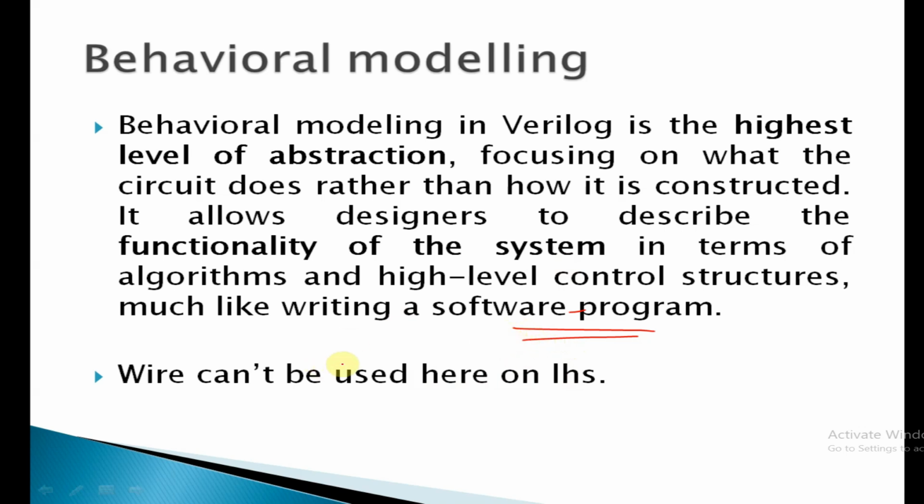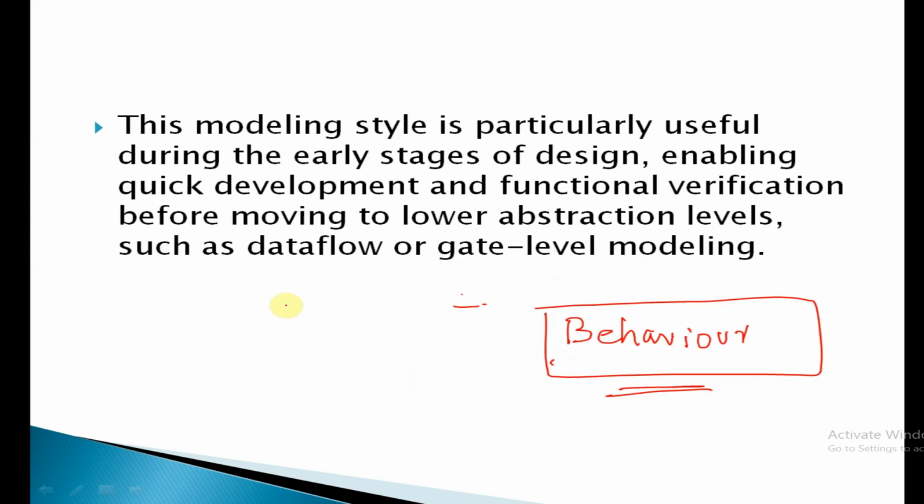That was the introduction to behavioral modeling. This modeling style is particularly useful during the early stages of design, enabling quick development and functional verification before moving to lower level abstraction levels such as data flow or gate level modeling. If some specification is given to you, you focus on the behavior of the circuit and write your Verilog code using behavioral modeling.